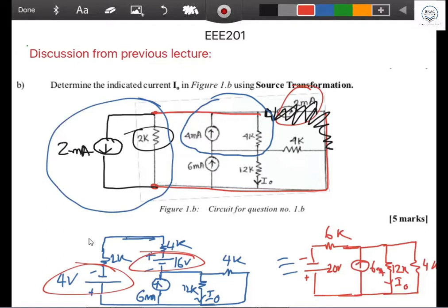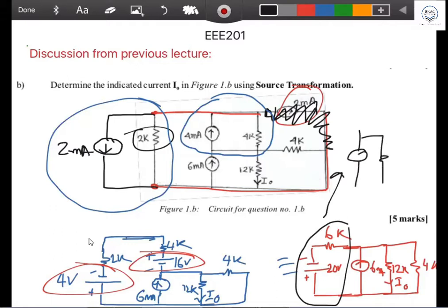Now you have to go for another source conversion of this thing, that is current source. If in current source, then 2 current sources you have to combine together into 1 current source, then your current division rule. After that, you can go for current division rule. You go from here, you can get it like this, like that, another and another one. There is another one coming together like this. And these two, you have to combine these 2 current sources into 1 current source.